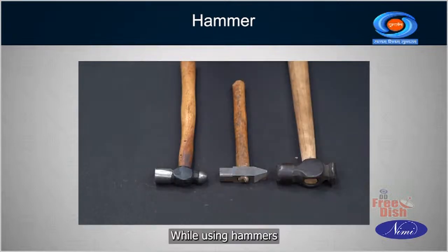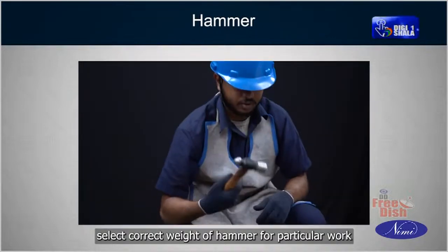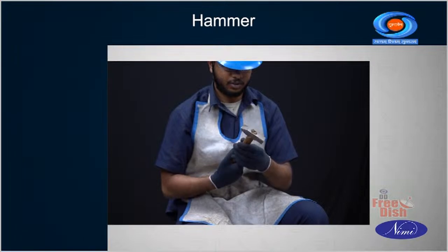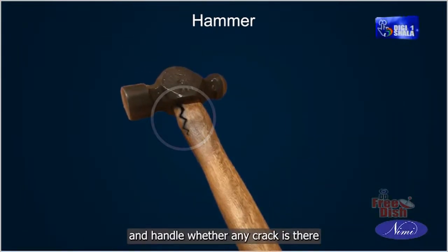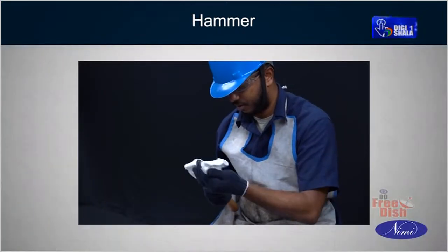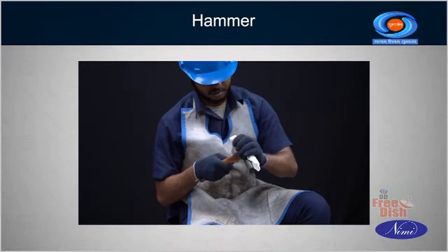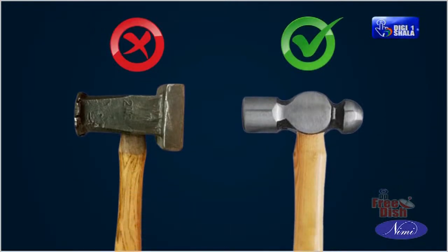While using hammers, select correct weight of hammer for particular work. Check the hammer head and handle whether any crack is there. Ensure that the face of the hammer is free from oil or grease. Do not use mushroomed head hammer.